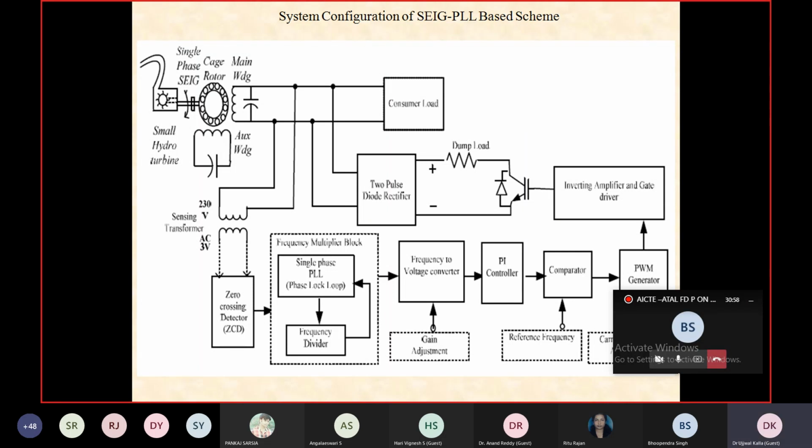It never creates any power quality issues for the system unless some inductive or capacitive load is connected in the output of this rectifier. If any inductor or capacitor is connected in the output of this rectifier, it will increase the THD, and the THD may increase up to 40%, 60%, sometimes 90%, 99%.